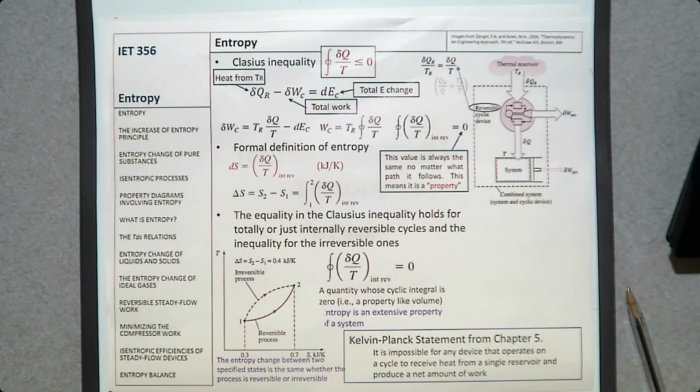If you can quantify the increase of entropy, if you have two different design directions, then one has this much entropy increase, the other one has this much entropy increase, then you can say this one is better design, this one is worse design because there's more irreversibilities because of the entropy increase.